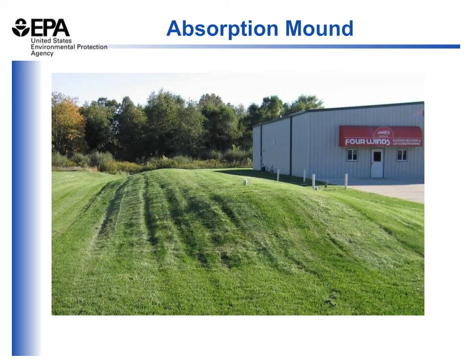As you can see here, the ground is mounded up to cover the dispersal facility itself, and then is backfilled with topsoil and planted with vegetation. Typically, you're only planting grass over a system like this because you don't want to grow vegetation whose roots would impact the dispersal of the effluent. The material that's used to create the mound is typically good, clean sand to allow the effluent to percolate down into the ground. In addition, the topsoil at the natural ground level needs to be removed and replaced with clean sand, so there's no breakout of the effluent at the ground surface.